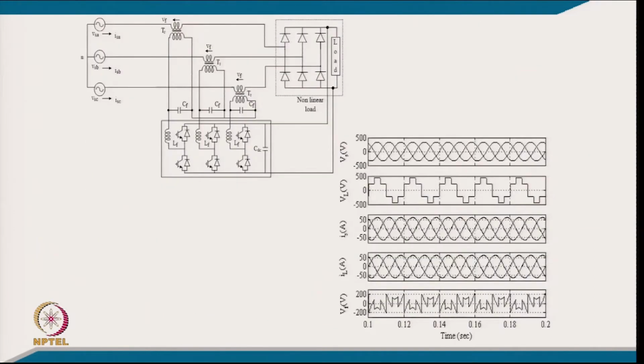Well, this is the total system. Here we again have the non-linear load in which the capacitor is connected at the DC link, and then we have a series active filter. The role of the series active filter here is, first, to maintain the sinusoidal supply current in phase with the voltage, so that it is unity power factor, with no harmonics and no reactive power on the supply.